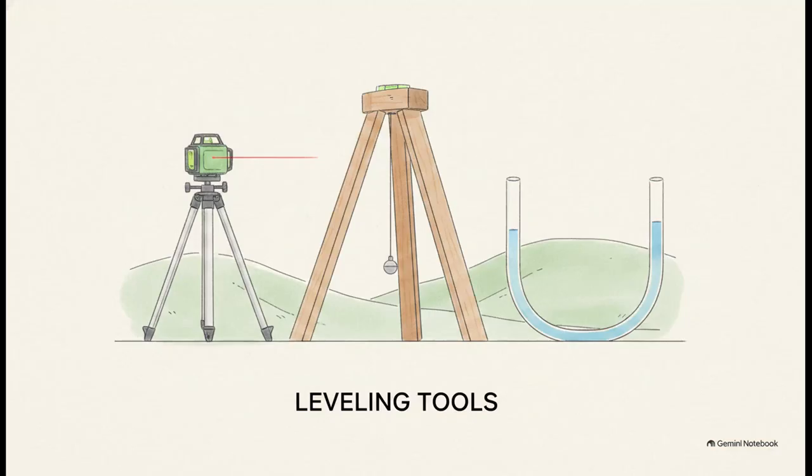Which brings us to Section 5, actually building water harvesting structures. Now we take those contour lines and build physical structures in the dirt to safely intercept the runoff. But to ensure these structures work, their tops must be perfectly level. If they aren't dead level, water finds the low spot, concentrates there, and boom, blows out your entire earthwork.